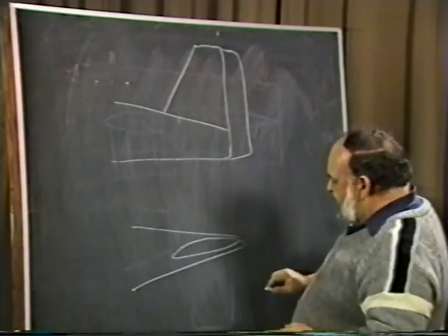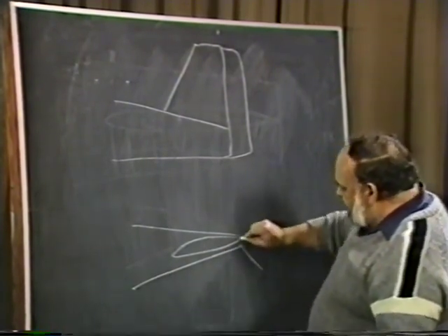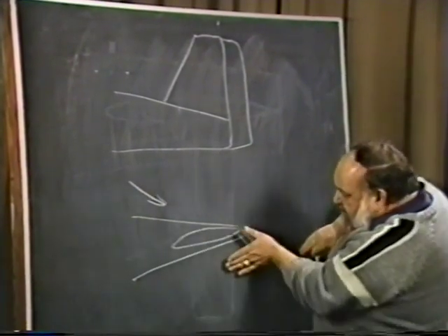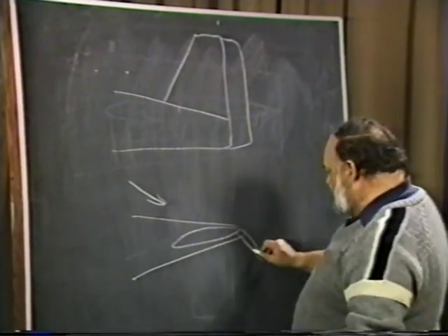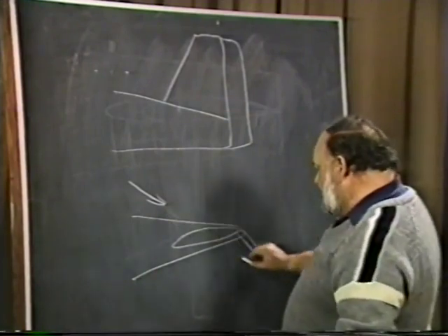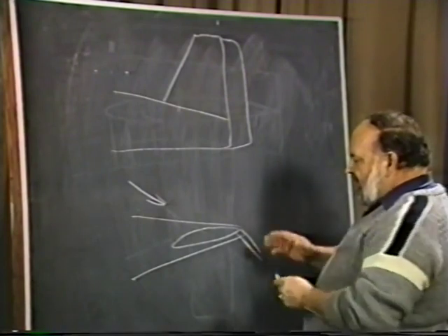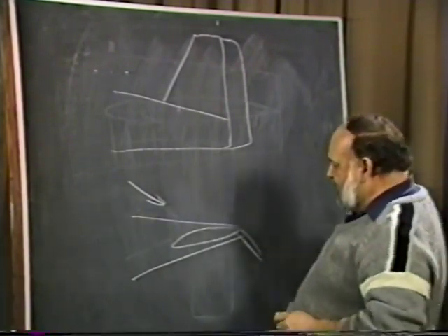Here is your surface. If you want this thing to yaw and deflect the surface like this, you will then start to twist the airplane over and it'll be flying through the air like that. So here's a peculiar airfoil. You can look at it just as if it's a wing with the flap deflected on it, and it's going through the air with this peculiar kind of angle of attack, you might say, to it. It's not like the normal wing flap configuration would be. It's cocked over and it's going through the air like that.